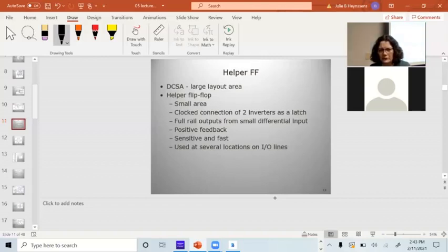So what they do is along the bus, once they take the outputs from the sense amp, those outputs are going to have to drive really long lines back into the data output multiplexer. So there's some really long lines in there, to keep the signal...